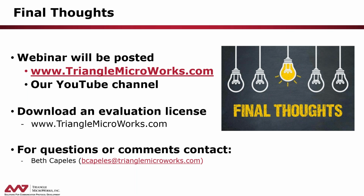Test Suite Pro is a test client, so it's designed for testing servers and publishers. DTM is the server simulator primarily. DTM does client functionality as well, but it's primarily the server simulator. So if you're looking at testing a client, testing an HMI, testing a gateway for the client side, then DTM is the tool to simulate the number of devices you need to exercise the client.